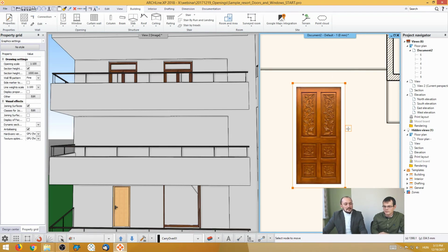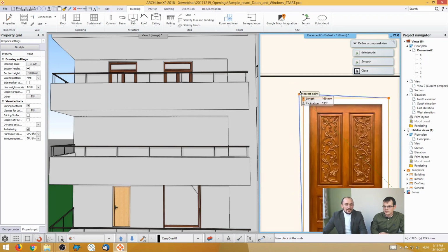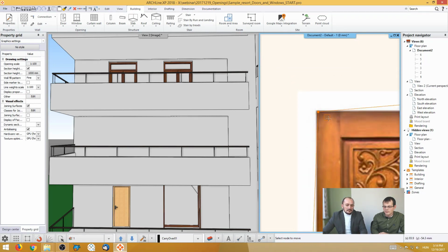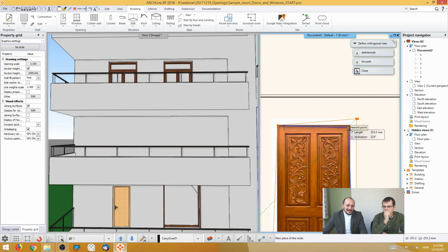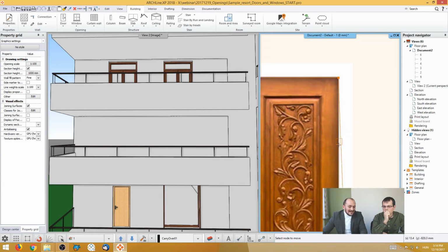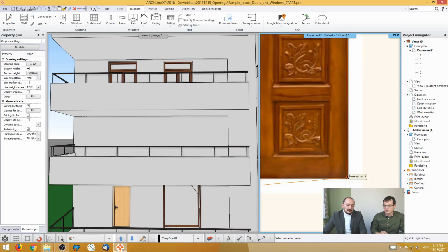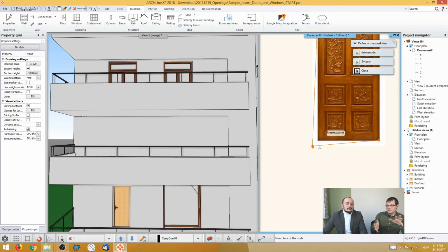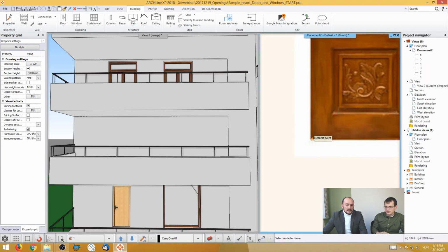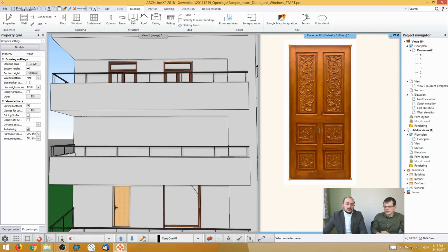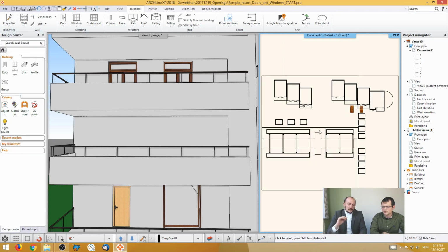This way you actually tell the software what the corner points are of an imaginary rectangle that you can see on a sometimes perspective photograph. Now it's not quite like that here, but you could even straighten out an image if it's at an angle. That's exactly what I want to show. So you just match these corner points to the original, sometimes perspective photograph, and then you hit enter, and the software turns it into an orthogonal material with perpendicular edges.